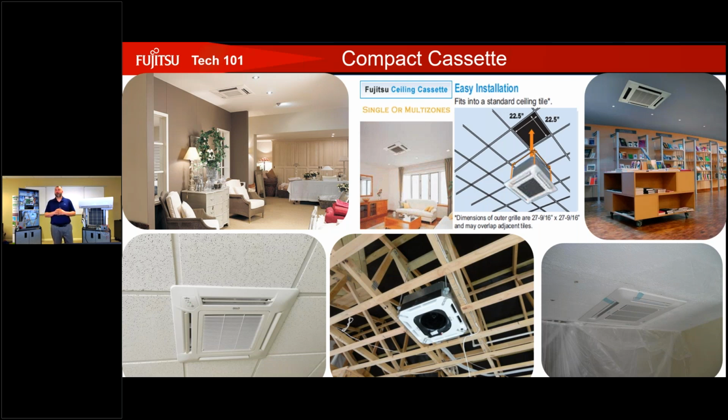Now getting to another thing actually with that picture, if we're thinking about serviceability afterwards, one thing we want to do is make sure that we actually have access to it. So if this home right here is not the top floor, how are we going to get in there to actually service it? If it's not in an attic, where is our service? So we might need to install some sort of access panel or something along those lines. So keep that in mind as well.